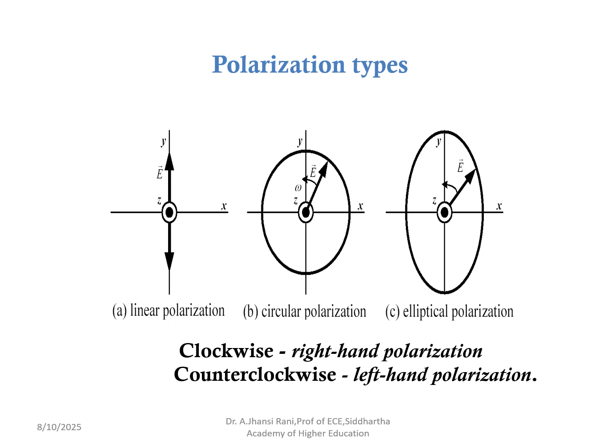In elliptical polarization, that is Ex plus jEy or Ey plus jEx, depending upon right-hand or left-hand polarization. Right-hand polarization, or clockwise, means that with respect to time the electric field is rotating in the clockwise direction. In anti-clockwise or left-hand polarization, with respect to time the electric field is tracing the anticlockwise direction. That depends upon the orientations of the electric and magnetic fields.